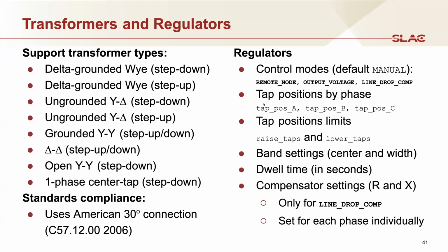And then based on those, you'll see the tap positions change over time from what they would have been set initially. If you're using manual, the tap position remains unchanged. You have to change it yourself, which you could perfectly well do either from SCADA data or from some external control strategy you want to impose on the model. Again, using Python, this is relatively straightforward.